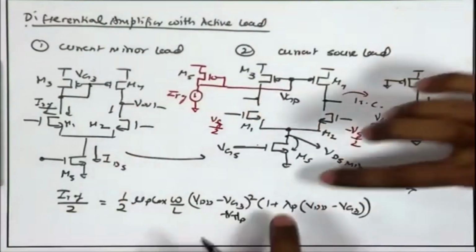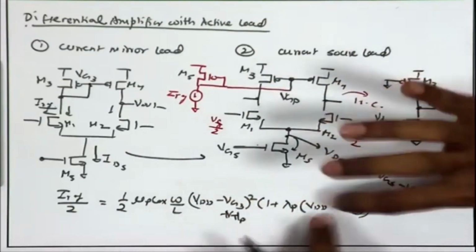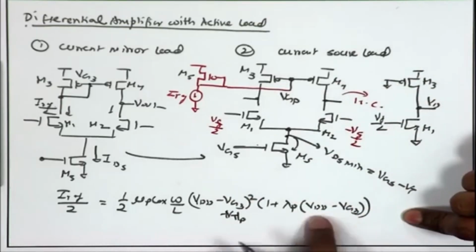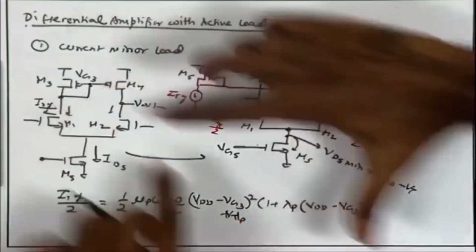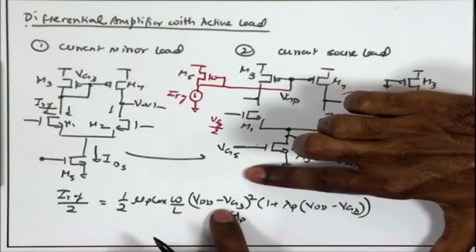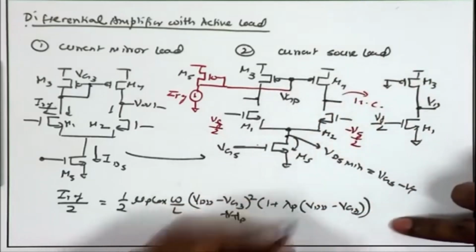Here the V out is not strongly dependent upon lambda, and remember, when it is dependent upon lambda, the problem is that lambda is very small and it requires a very large change in VD, the source to drain voltage, to accommodate for any imbalance, whereas in case of the quadratic dependence, it is a much stronger dependence on VG3. So, here VG3 is getting dictated by the quadratic dependence. I can altogether ignore this value.